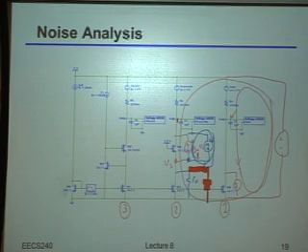So now, just to make sure that that's clear, let's do another comparison. Who thinks that current source number 3 will have less noise than number 2? Okay, well, that's good. Hopefully that's the obvious one. Who thinks it'll have the same or about the same as number 2? Again, we're comparing 3 and 2. So 3 is the gain boost, and 2 is the cascode. Okay, so 1 brave soul, 2 brave souls said it's the same or about the same. Who says it's 3 brave souls? Who says it's more?